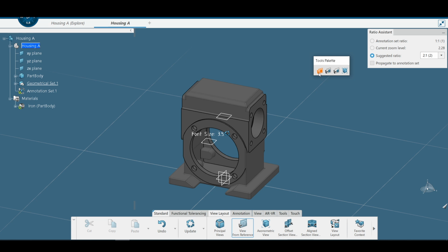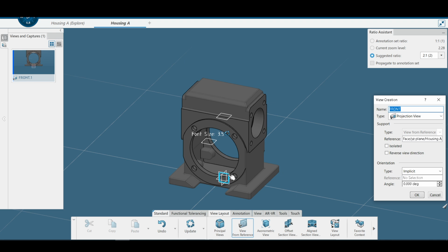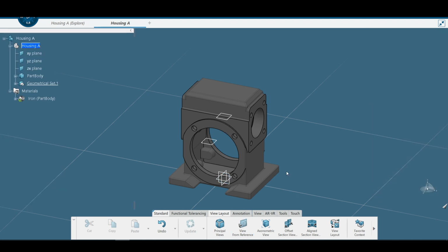Okay, along with the origin and axis system, the frame gets automatically resized to accommodate a new annotation. So activate the view to create the annotation. You just click activate, and see the view. It will automatically take the bounding box. Okay, see here, front view. Just close this one to activate the plane for the new annotation.